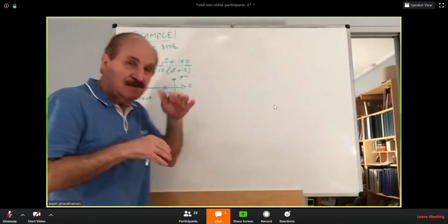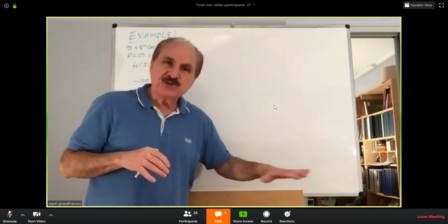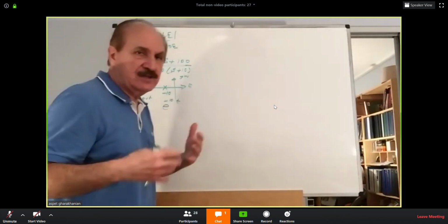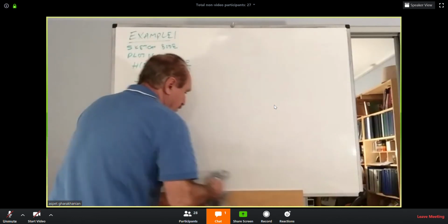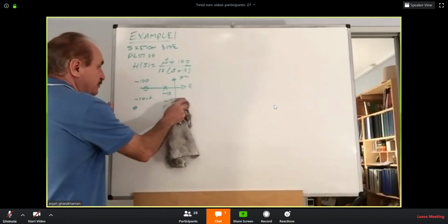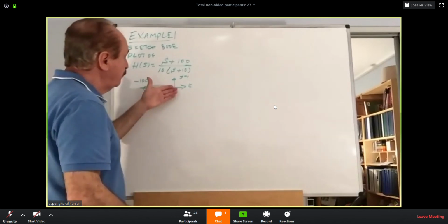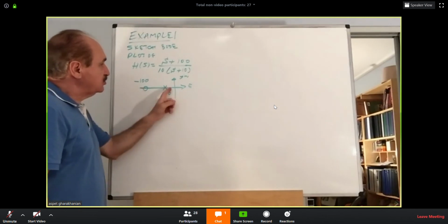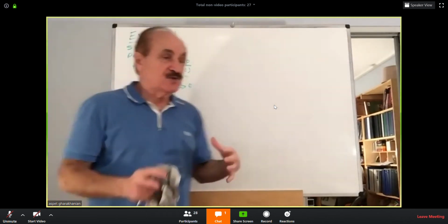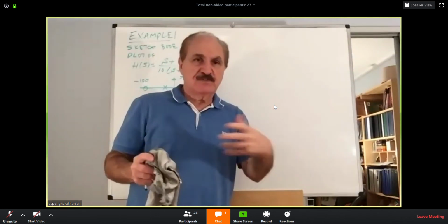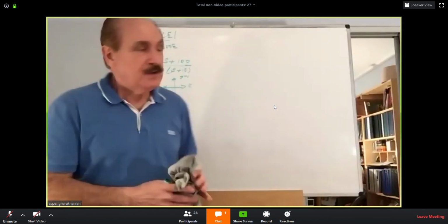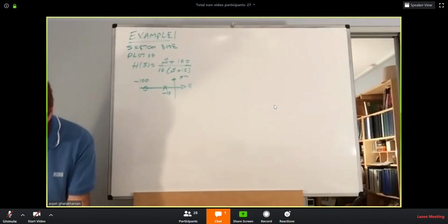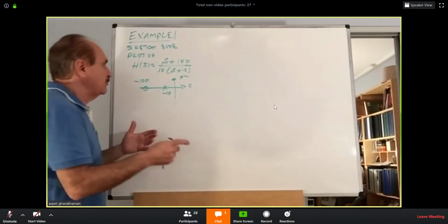That decays, but much slower. So the one that decays much slower is called the dominant pole. It's by the distance. So remember, the closer the pole, the more dominant it is. If the zero was closer than the pole, the transfer function would be dominated by the zero. So the closest one is always the dominant one, either pole or zero.